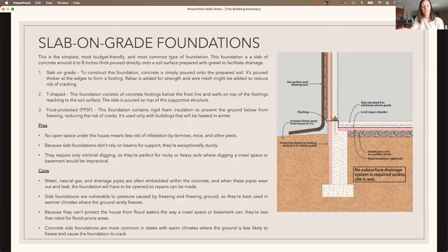So in places like California where they have earthquakes, I know they don't have basements because of that reason. Then what kind of foundation do they have? I think they have a lot of slab on grade, or in areas that are closer to the water, they probably have a lot of crawl space or pier and beam foundations, just to make sure that they don't have flooding issues. I think it would depend how coastal you are versus inland in California. They don't really have the freeze factor there either.